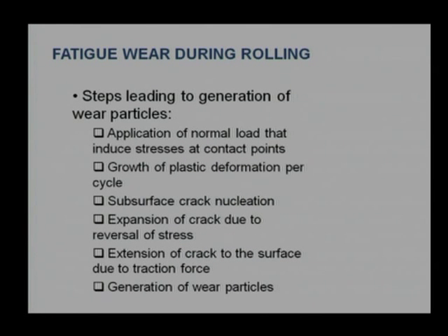We discussed fatigue due to sliding motion, but there is another fatigue which is more common, that is what we call fatigue wear during rolling. We know very well rolling induces very high concentrated stresses, or we say that contact stresses are generally very high in rolling motion, because the area of contact is very low.